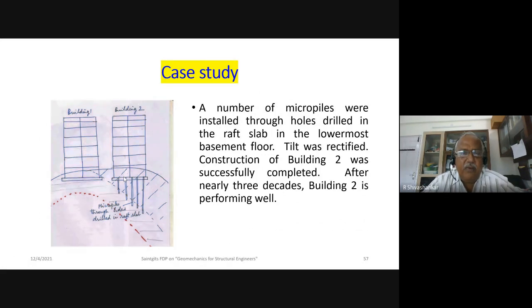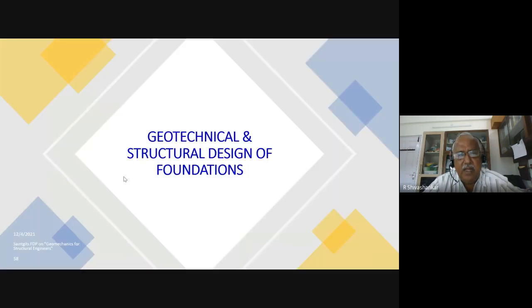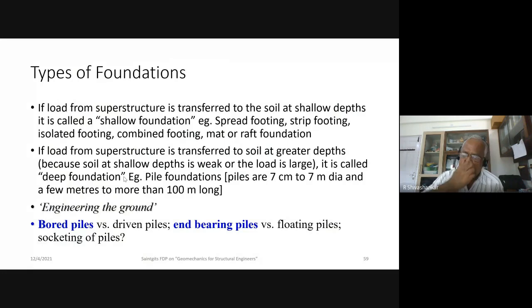You can't take it for granted that just the adjacent site will be the same. Even 5 meters, 10 meters away, the soil could be entirely different. So every project has to have a separate soil exploration.